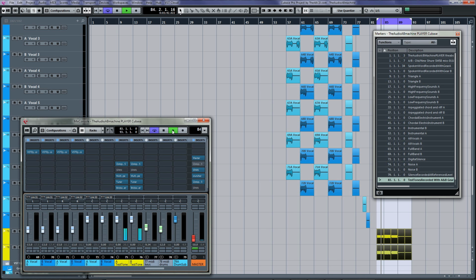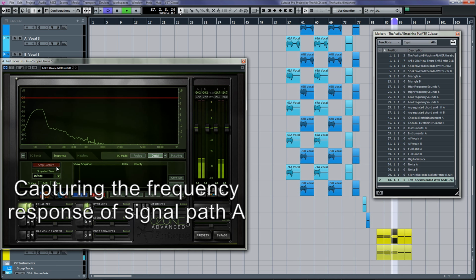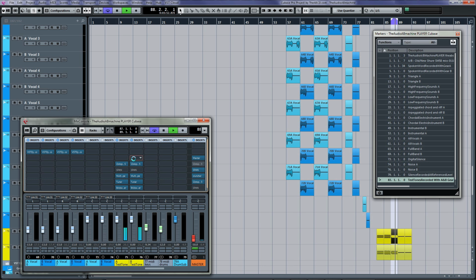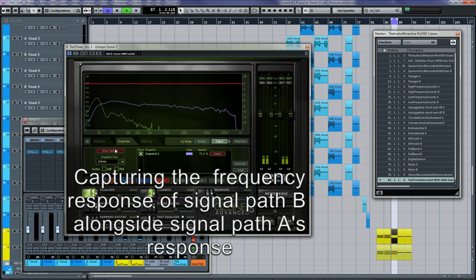As described in the manual, carrying out this type of advanced comparison is required to determine if two microphones are matched enough in frequency response and noise levels to be considered a matched pair of microphones. Matched pairs of microphones are required to carry out comprehensive tests of such things as microphone preamps to each other.